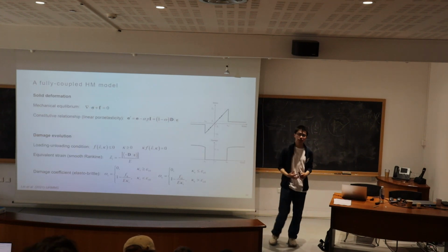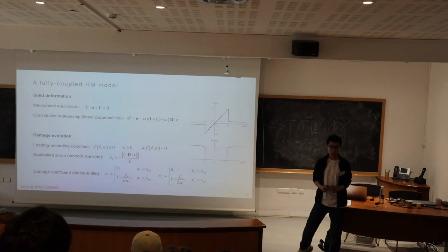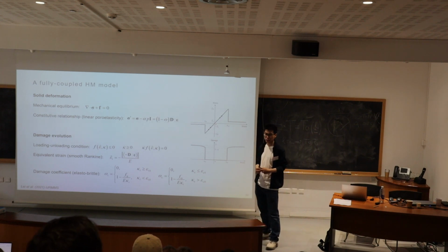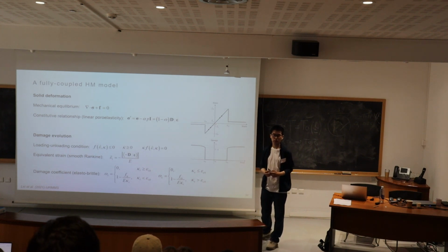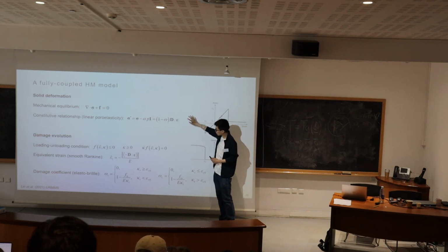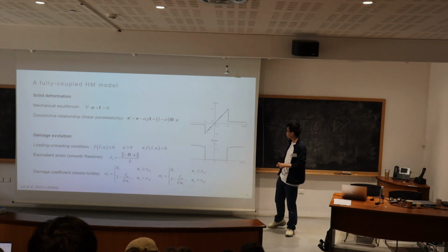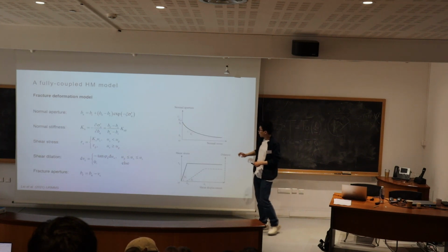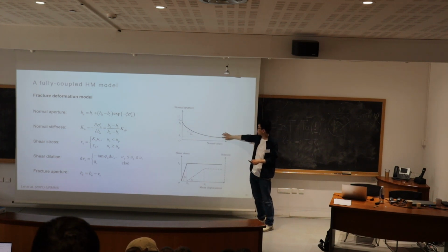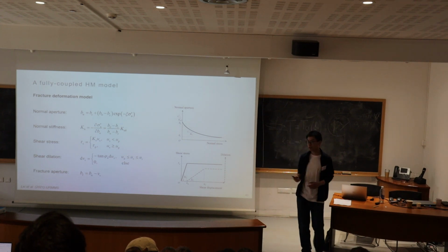To understand this, I use my numerical model, which is the fully coupled hydromechanical model, to capture the coupled hydromechanical processes during the fluid injection into the fractured rocks. I modeled solid deformation. I used a damage mechanics model to simulate the fracture propagation, and an elastoplastic model, which I also mentioned before, to simulate the aperture evolution of the fractures.